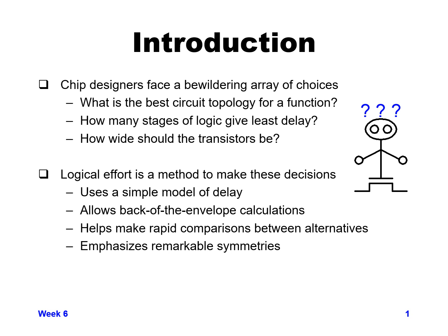And if you have multiple stages, how wide should your transistors be? You might say the wider the better, the faster they'll be. Again, in reality, that's not always the case. You can wind up using wider transistors in some places, and it'll slow down the stage before it because it's more load on the previous stage. So you need to choose the number of stages and the width of your transistors very carefully.